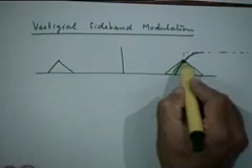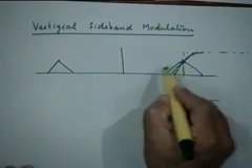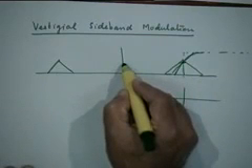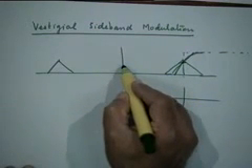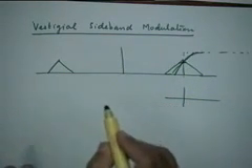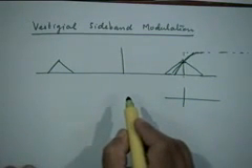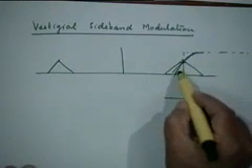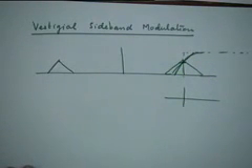Why low frequency? Because these frequency components actually belong to the low frequency component of your original message signal. So if your message signal has significant low frequency content, then SSB will create all these problems for us because of the need for sharp cutoff, which either we can't do, or if we can do it, it will be associated with these kinds of distortions.